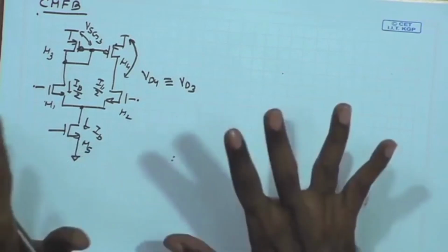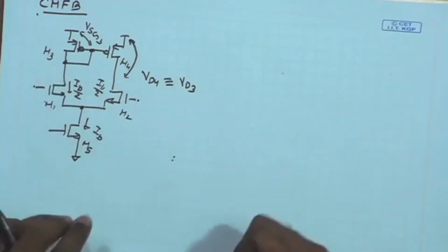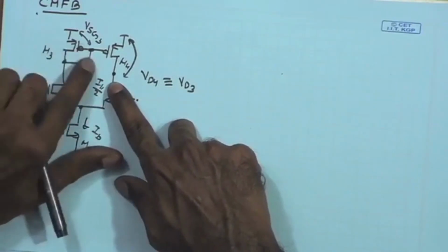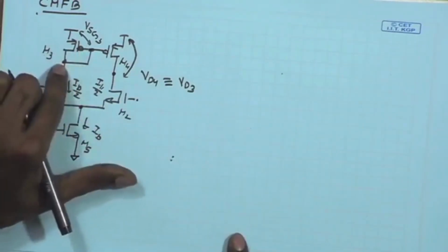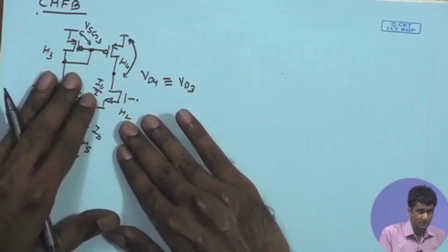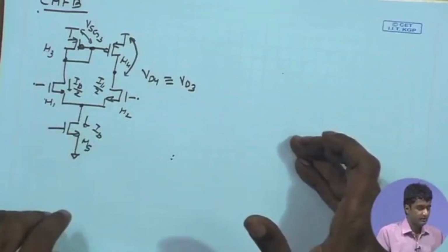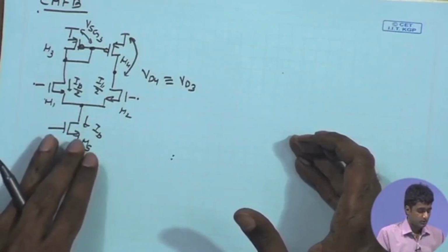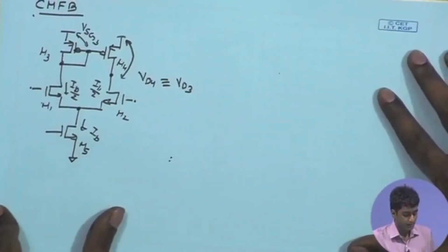So, the differential amplifier with current mirror load is self biasing. It provides an output DC point which is well defined, which is equal to the VSG of M3, and therefore, we can take help of the differential amplifier with current mirror load to bias our fully differential amplifier, which does not have a well defined DC bias point. So, let us look at the overall solution that we are going to apply.